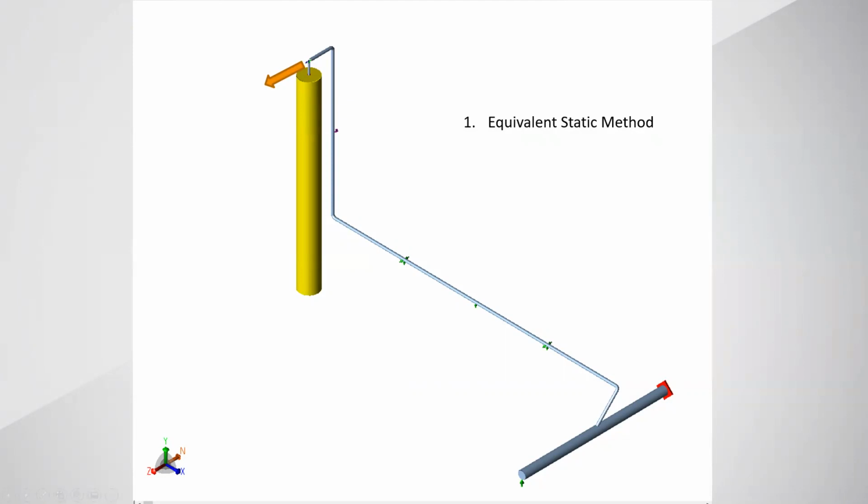Okay, so we'll have a high pressure here and a low pressure there, which result in a net force in the Z direction, in that direction. We'll have a vertical force, because we'll have a high pressure at that end, low pressure there, and of course, as the pulse moves through the system, we'll get a net force in the negative X direction in that part of the pipe.